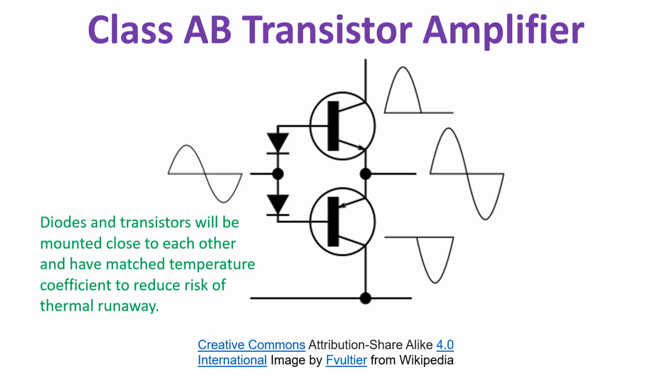Class AB amplifier is intermediate between Class A and B in that conduction angle theta is more than 180 degrees, so that each of the two active elements conducts a little more than half of the time of a signal cycle, so that the crossover distortion mentioned in the case of Class B amplifiers is minimized. It is also possible to further reduce crossover distortion by using negative feedback.